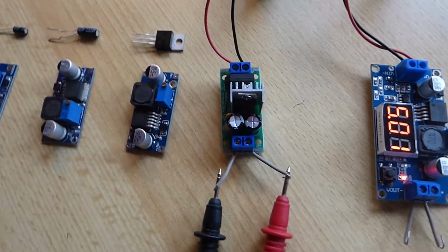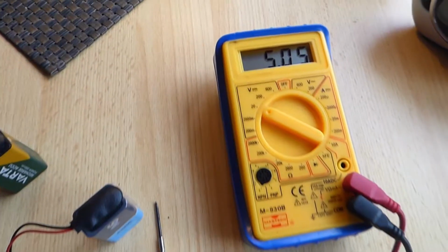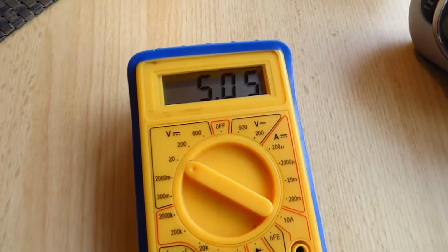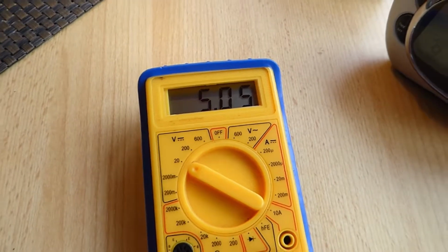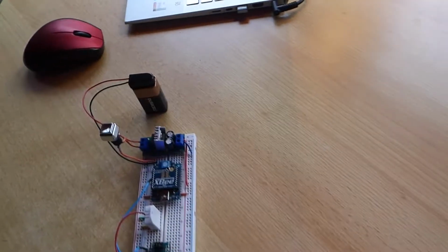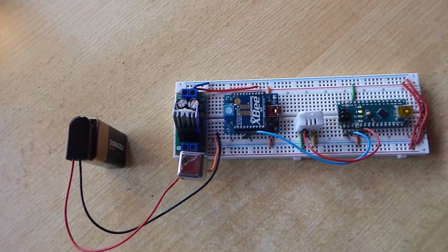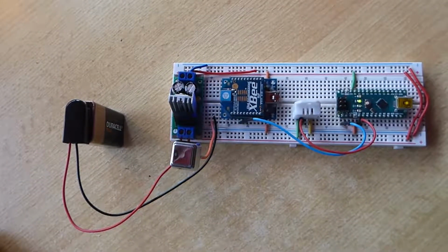In the last video, I preferred the L7805 5-volt 3-terminal regulator power module. This was because there were only two inputs, which could be AC or DC, with a range of 7.5 volts to 20 volts, and two outputs, giving automatically a 5-volt output. This regulator, with a built-in heatsink, unlike the 7805 5-volt regulator, is much safer to use in educational establishments. Although the previous regulator circuit is still recognized throughout the world, it can burn your fingers if incorrectly installed.